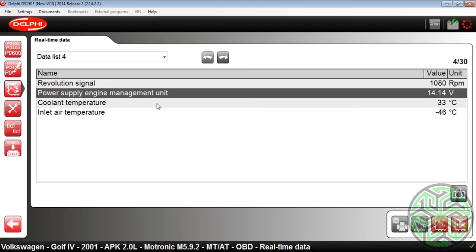Okay, another good point. Like I said before, with my alternator, I was only getting about 11.5, 12 volts out of the battery. We stripped the alternator, took some Clean Green, scrubbed it out, a little bit of elbow grease and some TLC, and yeah, there we are, 14.14, steady.